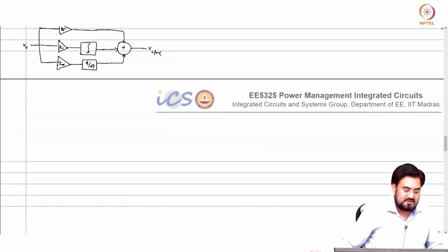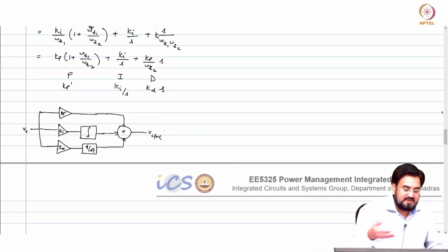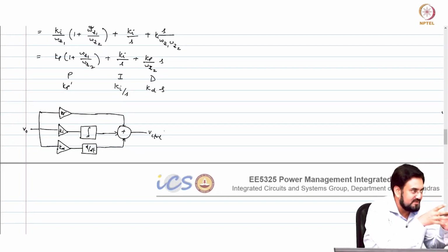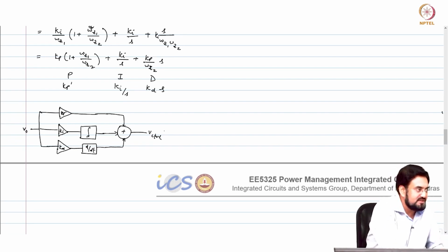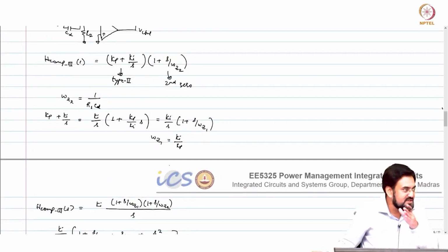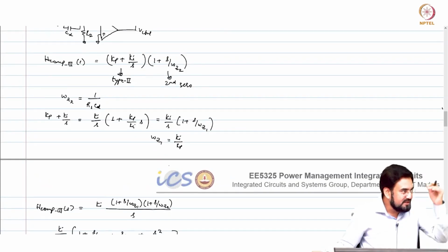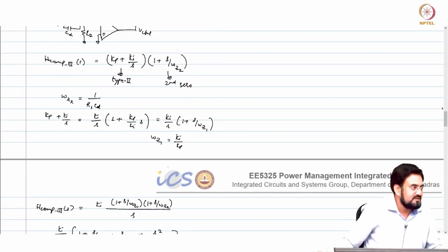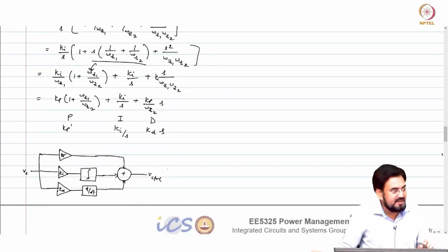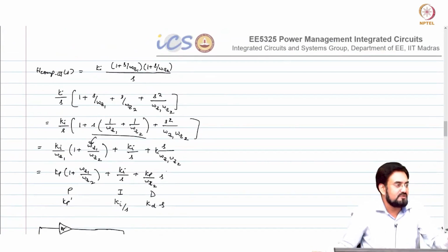Okay. So, you cannot control independently here, but here you can control independently, and that is what people do when they say they design a PID compensator. This is used in motor drives also. They control all 3 parameters independently, but ultimately they are doing the same thing. They are just positioning the 0 and adjusting the gain, that is it.